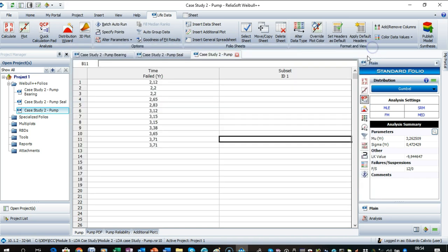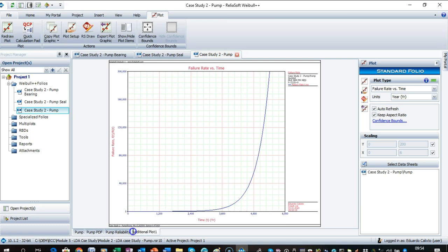So here, if I look at the pump in general, it's telling me to do such inspection later than if I look at the bearing, and that may be a dangerous point. So what I'm trying to demonstrate here is that if I have the data at an equipment level, I just do some inspection of the pump in 1 year, and then of course based on my experience I know that the components that are expected to have failures are the bearing and the seal.